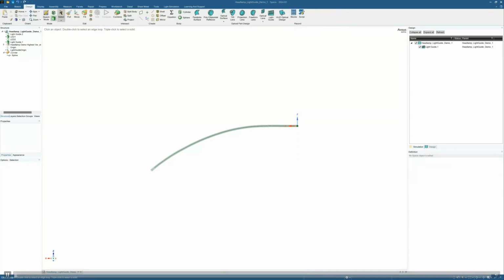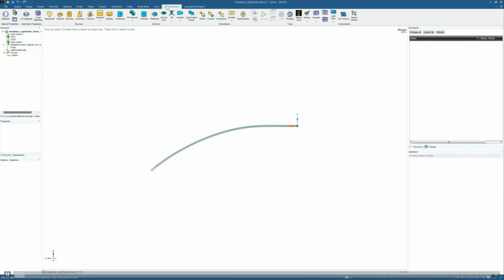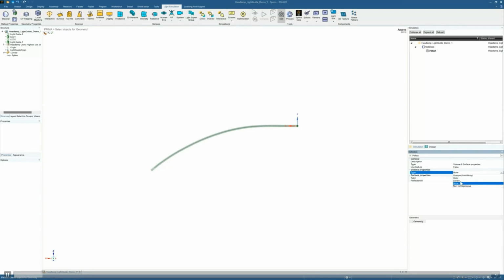So we're going to hit the simulation tab as well next to that design panel, because that's where everything's going to show up for this light simulation. So we're going to start by adding some material. Anything that you're going to want to select in your CAD-wise or geometry-wise that you want to see in your simulation, you have to add an optical material to it, even if it was already mechanically defined inside of, for example, SpaceClaim that we're seeing here.